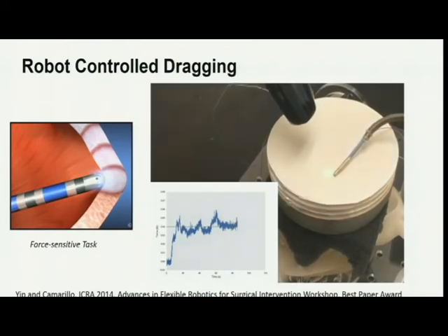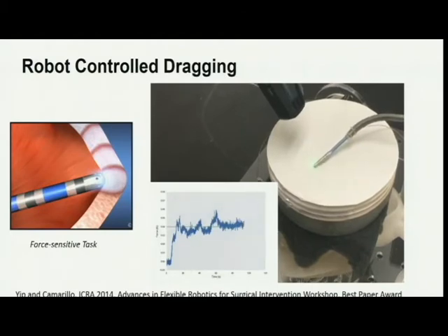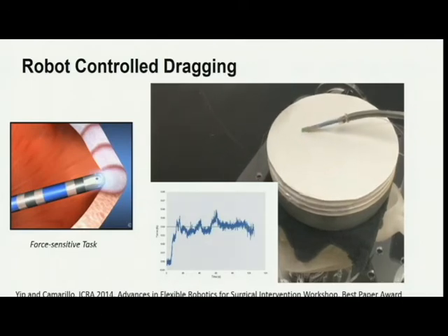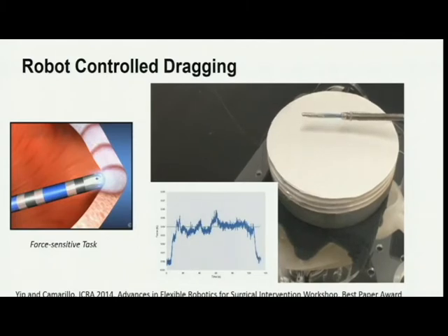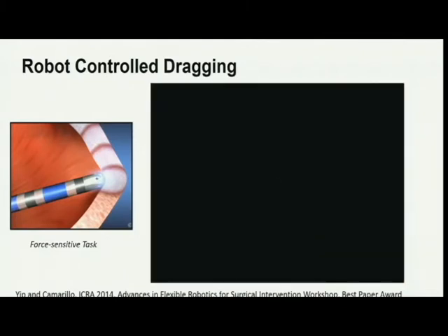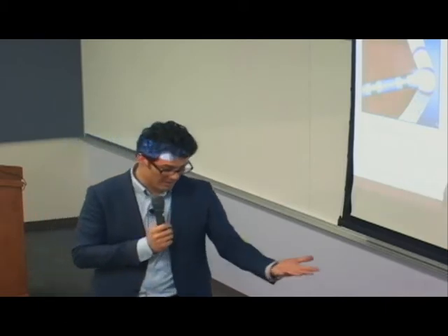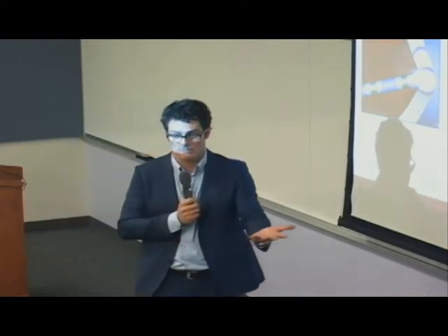Yes. No. Yeah, everything. Well, okay, so that's not entirely true. There is an initialization process, but it's very simple. You essentially just do a little wiggle before you start, so you exercise all of the actuators independently. There's your initial Jacobian. And then once you get into contact, we reshape the Jacobian so we don't update it anymore in the plane. But it is still learning. The Jacobian is it.